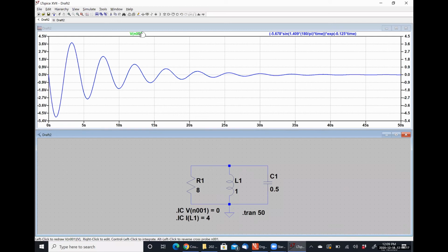You literally just add y at infinity to all of your y of t equations, but don't add it to the derivative. And then we get into general RLC circuits, which are more math intensive at the front end. And then once we figure out what the characteristic differential equation is, it's literally the exact same thing. So get used to doing these couple of steps that we did over and over and over again for the next 2 weeks.